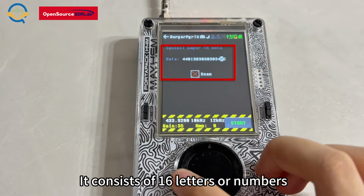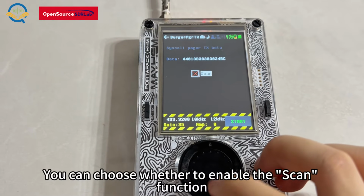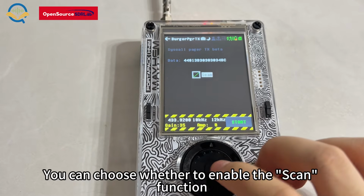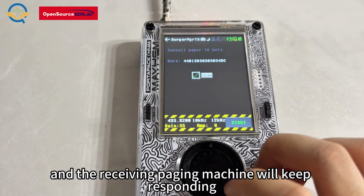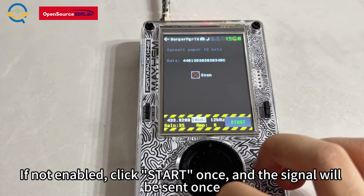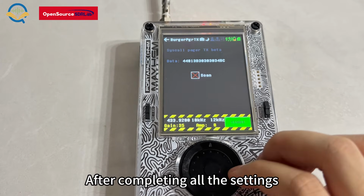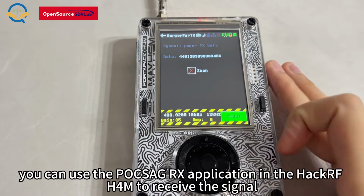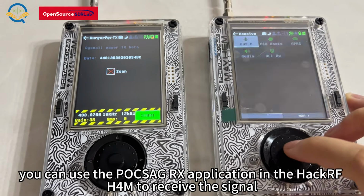It consists of 16 letters or numbers. You can choose whether to enable the scan function. If enabled, it means the signal will be continuously sent, and the receiving paging machine will keep responding. If not enabled, click Start once, and the signal will be sent once, and the receiving paging machine will respond once as well. After completing all the settings, you can use the HackRF application in the HackRF H4M to receive the signal.